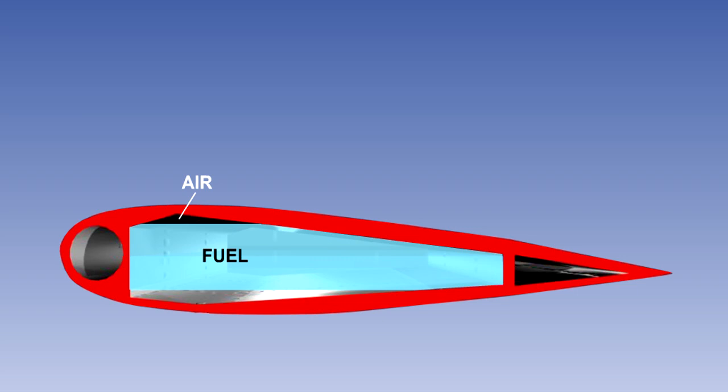Once the fuel is in the aircraft tanks, the main source of water contamination is the atmosphere that remains within the tank. If the tanks are topped up to full, then the atmosphere is excluded together with the moisture it contains, thus minimizing the likelihood that fuel will be contaminated.